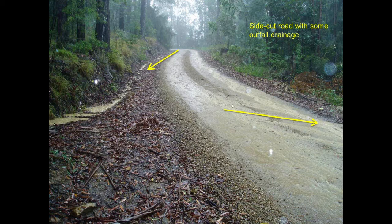Typically, in terms of a water quality scenario, it's best to have outfall drainage. It's easy to get the water off the road. You're less likely to create situations where you'll promote gullies or rill erosion. However, there are certain situations where that's unsafe, so it's not always practiced.